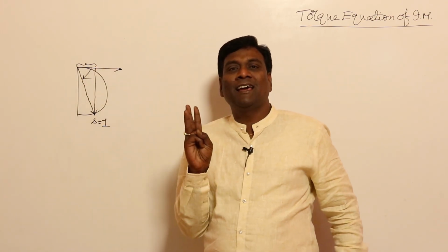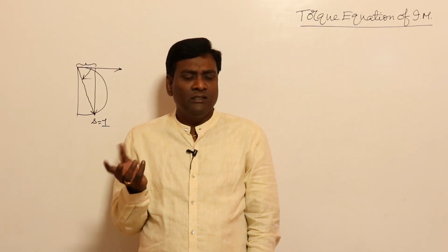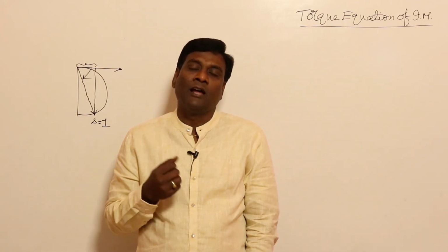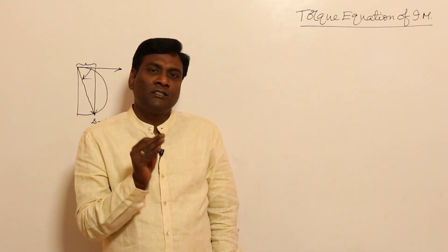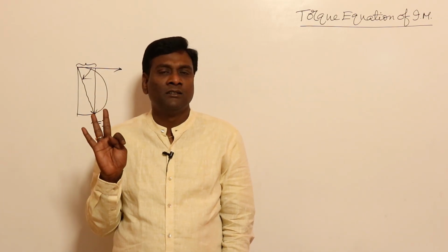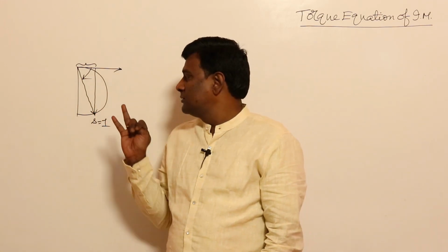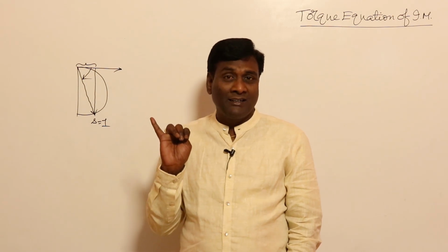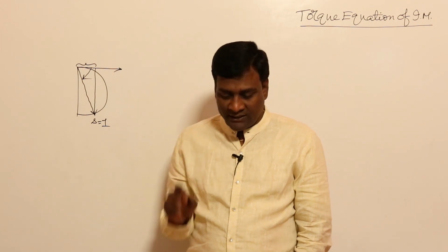So there are three characteristics primarily we have to analyze, apart from efficiency characteristics. Efficiency has its own significance, because losses, efficiency and power calculations are done. So what are the things we are going to discuss in induction motor? What are the characteristics? Torque speed characteristics are external characteristics. Our speed is nothing but slip, so torque slip characteristics. The second is current characteristics with respect to speed, magnitude of current, power factor characteristics with respect to speed, and then next is efficiency calculations.